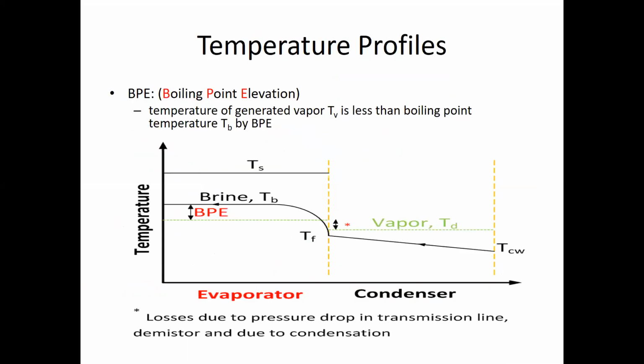After we described the system, we looked at the temperature distribution. In the condenser, there is an almost linear temperature increase from T cooling water to T feed. This increase in temperature is occurring due to the admission of the vapor coming into the unit. Then the feed flow enters the evaporator at TF. First it will be increased sensibly to the saturation temperature, and then evaporation is going to occur.